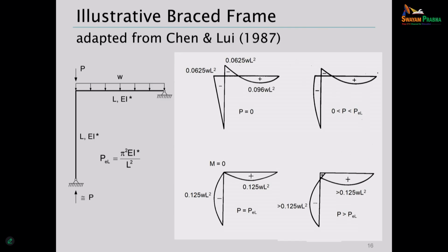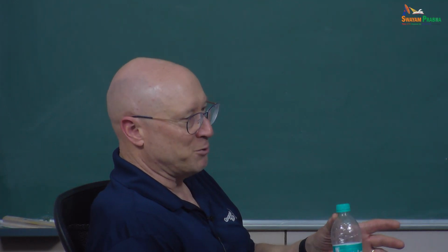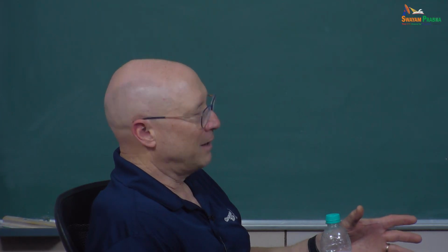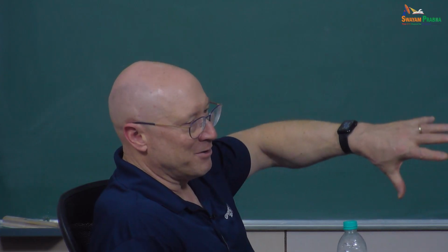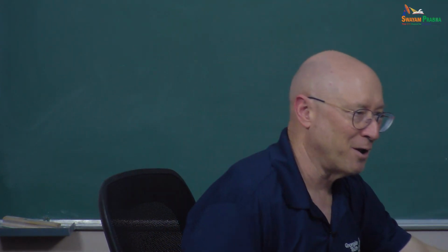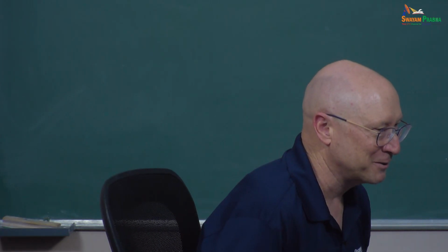I think the difference is from the case you're thinking of. If you do it with a spring, you're right, you won't get the 0. You should not exactly go to 0. But notice that here it's not a spring. It's a member with a uniformly distributed load. So we're starting out with a negative moment there at the knee because of that distributed loading on the beam. So that's a little bit different than the spring case.